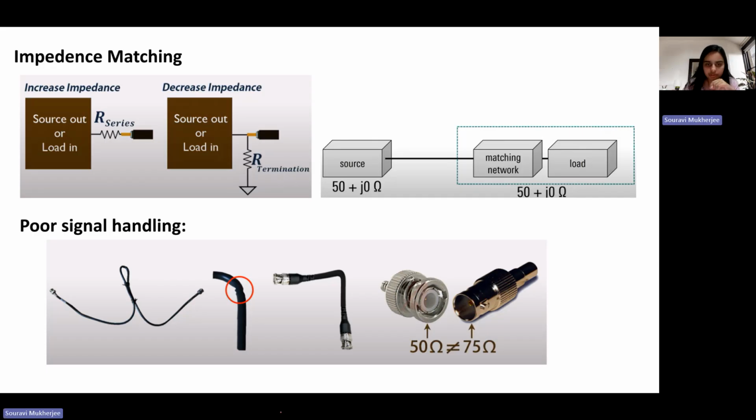These are very useful because while I'm doing my work, when we make circuits, you can understand this may look very simple, but these are very important points. Okay, the length of the coaxial cable. Suppose you have very large cables involved in a circuit and you're doing very sensitive measurements where time delays are very critical, then that can mess up. So you have to reduce your length of cables such that those problems do not come in.